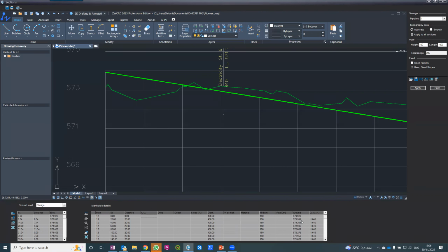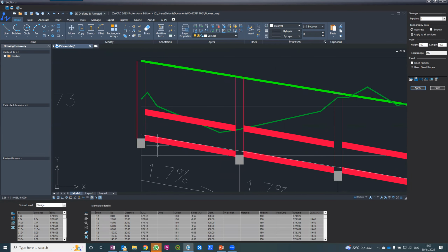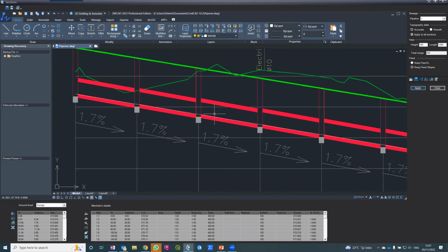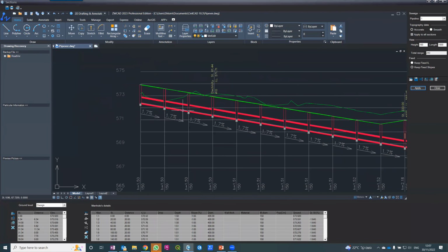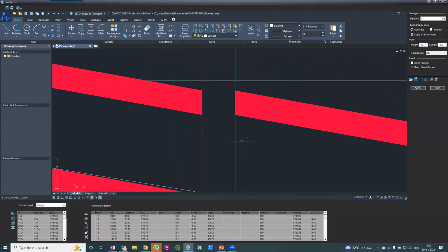From 1 to 13. I'm starting with a depth here of 1.5 meters. Depth of 1.5 meters. And I see that the ground is around 1.65. It's written here. So I will use more or less the same, 1.65. Press apply. And this is the pipe. I received the pipe. We know already that it's 400 millimeter. We know the manholes are 1.5 meter. And the problem is that I'm intersecting with my electric pipeline.